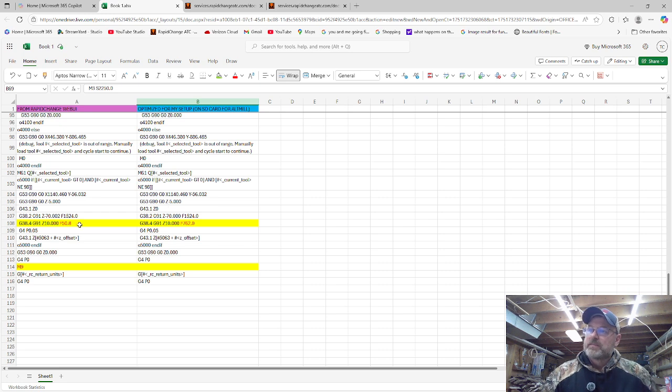And then this is where I have my feed rate set a little bit higher. So I think the standard feed was 50.8 for what I set in my macro for my tool setter. And so I upped that to 762 millimeters per minute, or whatever that is, because everything in here is in millimeters.